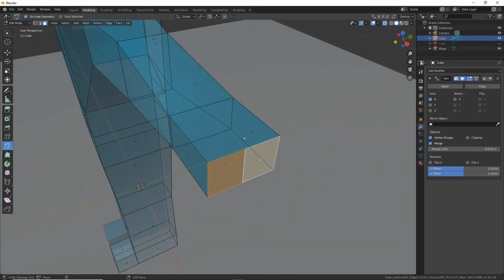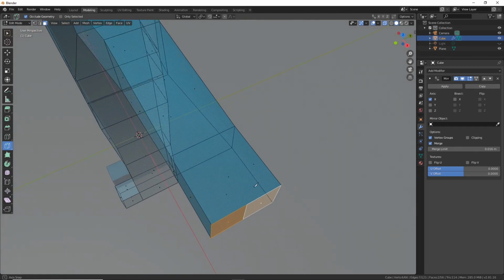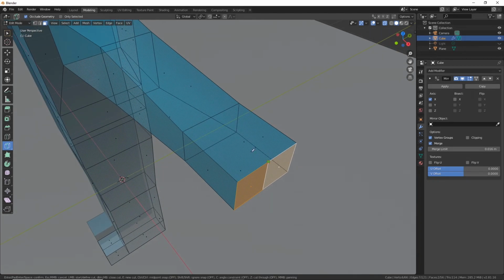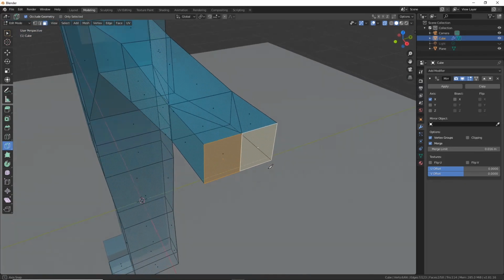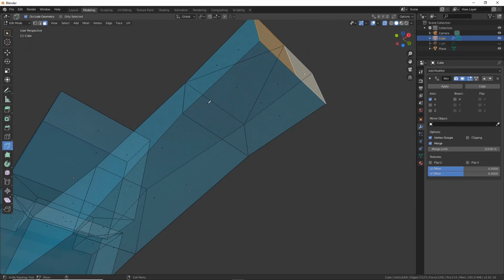Now I've got an n-gon here, which means I've just got more than 4 points. But to close that up, I can again draw this point to here that way, and from here to here. You can make this so that it snaps, but we can always just clean it up with the merge points. And then we'll do it across the bottom too.